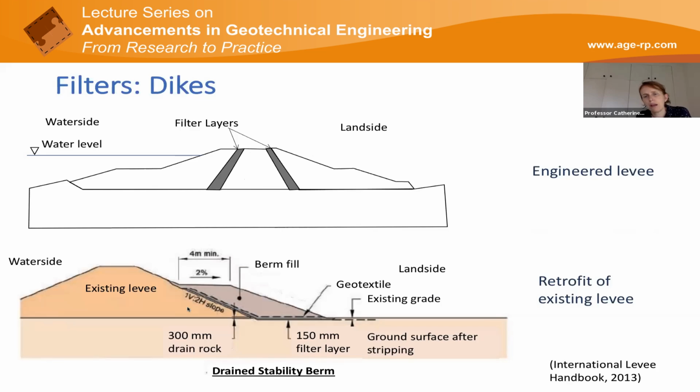I worked a bit on levee design in the US many years ago, and what you see there is those levees were never designed. They're quite different to embankment dams. They tend to be structures that evolved over decades, and the engineering comes into retrofitting them and improving their stability. And there we need to think about filters and the filter design rules that I'm going to talk about in this presentation.